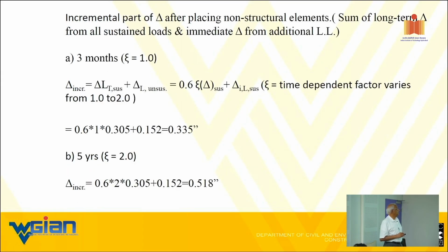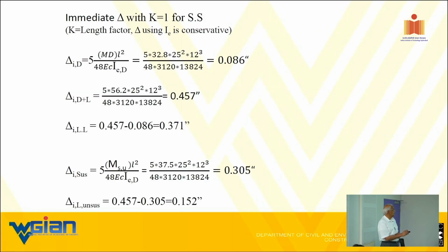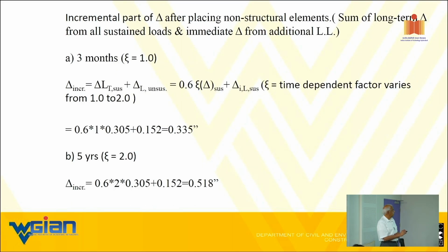There we go. The incremental part of delta, after placing non-structural elements, is some of the long-term delta from all sustained loads and the immediate delta from additional live loads. Now for 3 months, you can see we have already computed these numbers in the previous slide. You remember 305 and all?